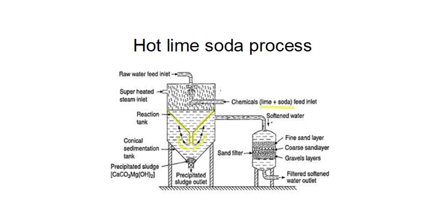So completion of reaction and the particle size growth, both of these aspects increase in rate in hot lime soda process. Once the water comes down, the precipitated calcium carbonate and magnesium hydroxide sludge comes down,